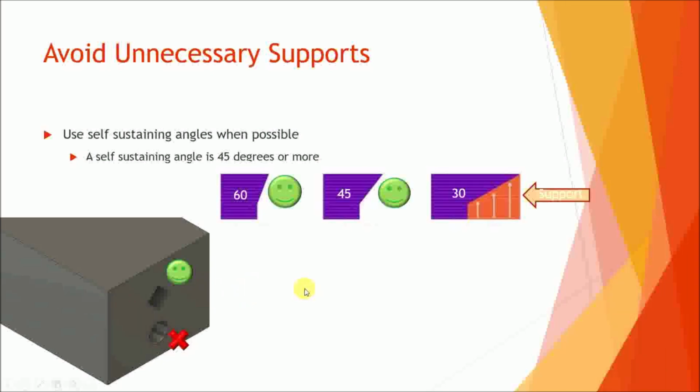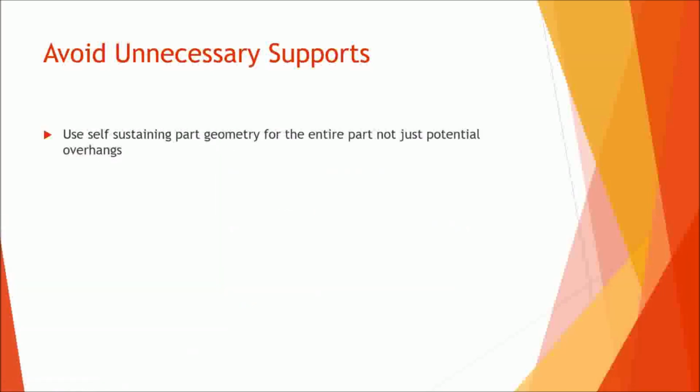Yep, already talked about using self-sustaining geometry. Try to use self-sustaining geometry when you're designing the entire part, not just a portion of it. Try to get the entire part to print without support material. That's kind of the goal. That's the most efficient way to do it.